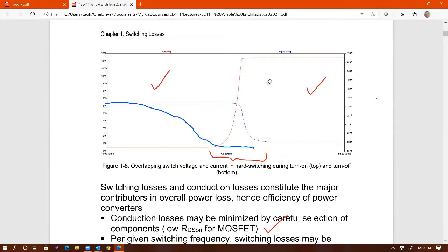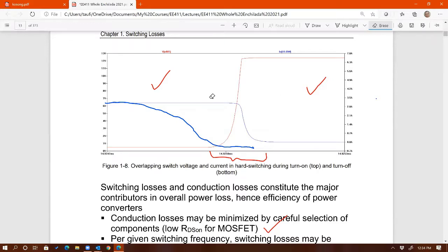Oh yeah, we could. So we could turn on the MOSFET. You're right, we are the ones controlling when the MOSFET is on or off. But the way the voltage or current shapes after you turn on the MOSFET is a function of the components that you put in the circuit. It just so happened that for PWM, when you turn on the MOSFET, the current jumps right away. It doesn't have to be this way.